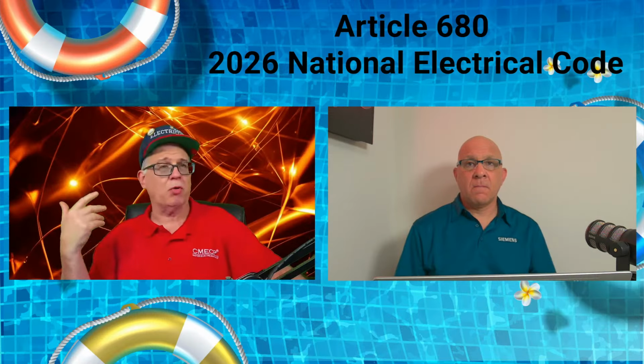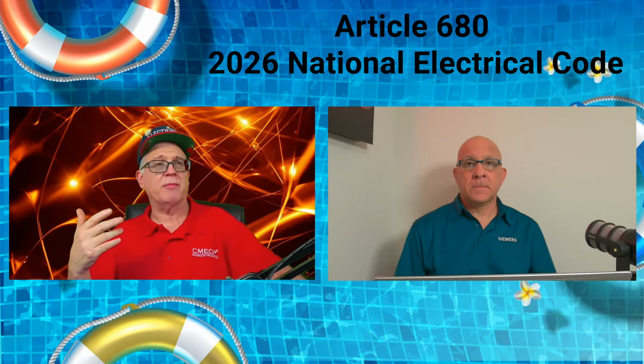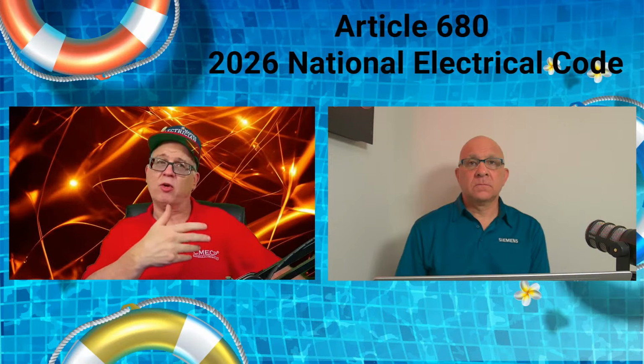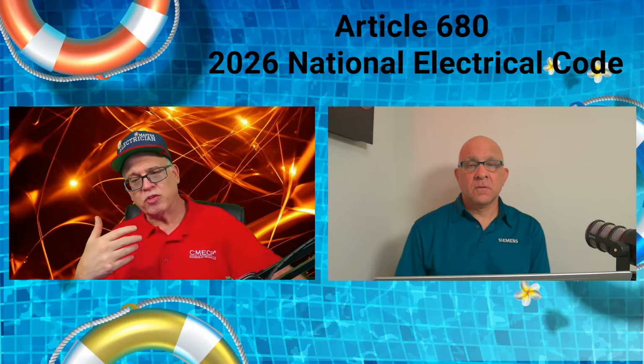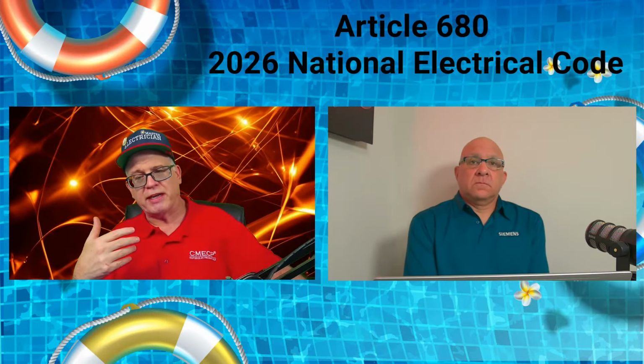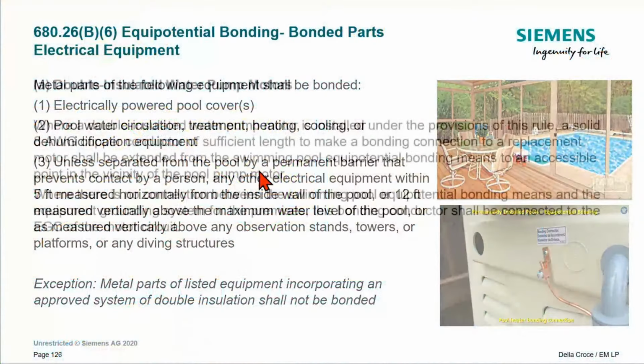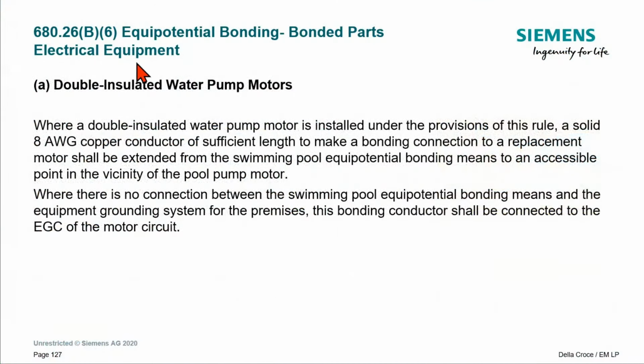The motor might be remote and separate from where the mechanism is that moves the pool. That's true. So that metal would be within 5 feet. That still would have to be bonded. So in this one, we're talking about the listed equipment that's incorporating an approved double insulated system. So we're going to use motor for simplicity's sake to be able to talk about it. And so that's going to bring us here to